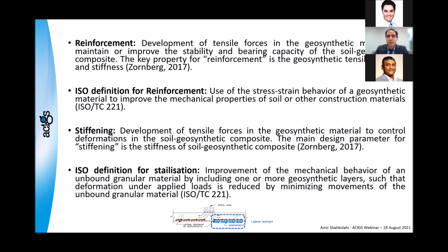Let's see some of the definitions in the market about reinforcement and stabilization. Reinforcement, according to Dr. Zornberg, is development of tensile forces in the geosynthetic material to maintain or improve the stability and bearing capacity of the soil geosynthetic composite. The key parameters here are tensile strength and stiffness. According to the ISO definition, reinforcement is the use of the stress-strain behavior of a geosynthetic material to improve the mechanical properties of soil or other construction materials.